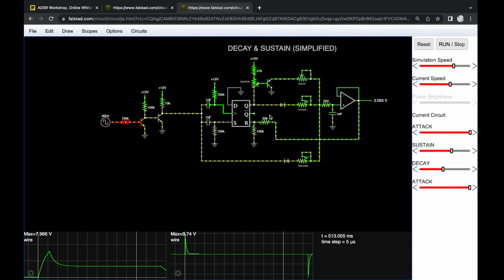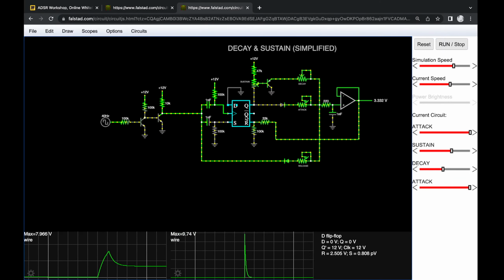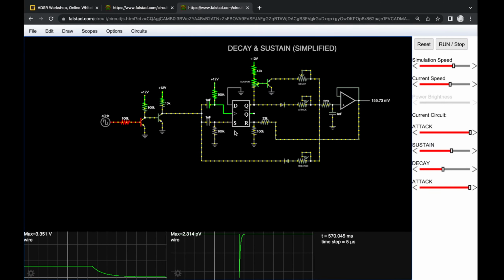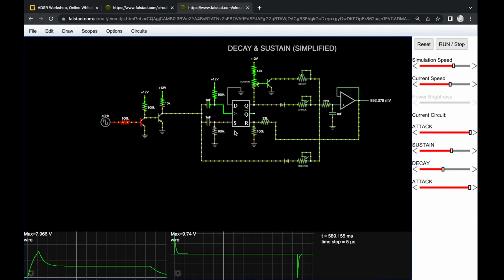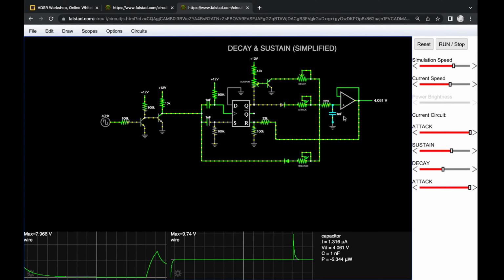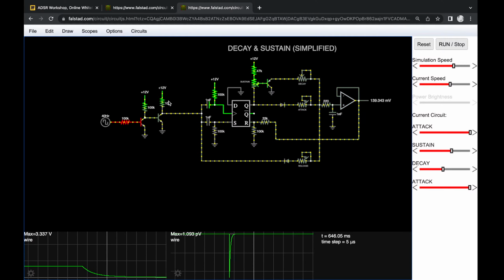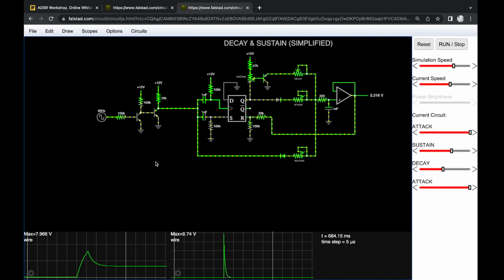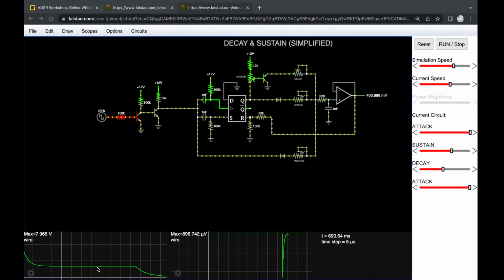And actually, the chip that I'm using right now on the breadboard houses 2 of these, so theoretically, if you want to build a module, you could build a twin ADSR with one TL072 and then some transistors to get this functionality over here. I hope that answered that question. I'm going to go back to the chat and check for more questions.